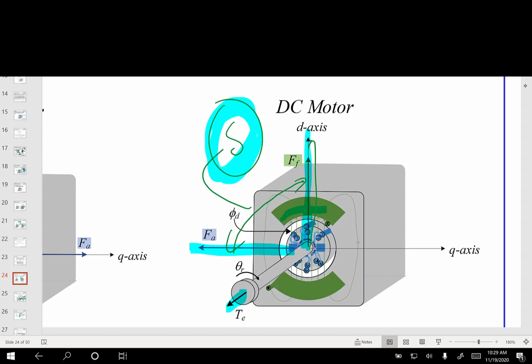Can I ask a quick random question? Yeah. Just because I have a lot of power tools, are brushless motors basically a DC motor that uses electronics instead of a commutator? You're right, it is, but a brushless DC machine is actually a synchronous machine. All really efficient motors have permanent magnets in them, okay? So think about a DC machine. It's got these brushes.